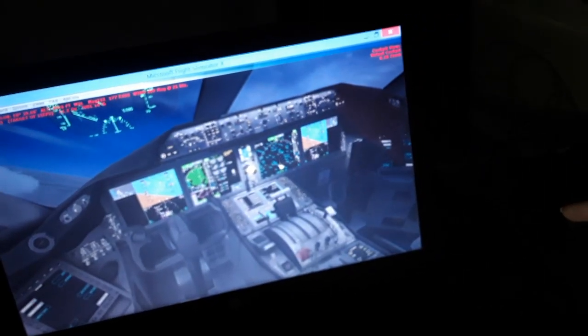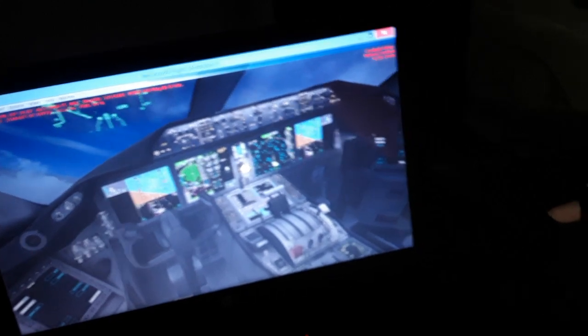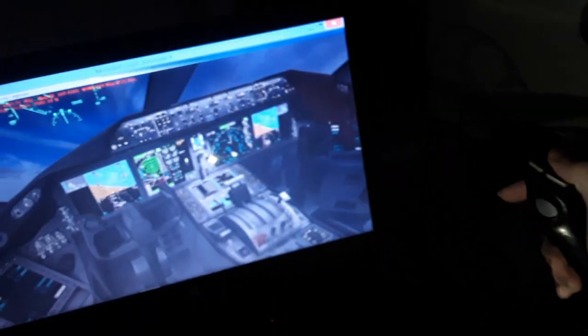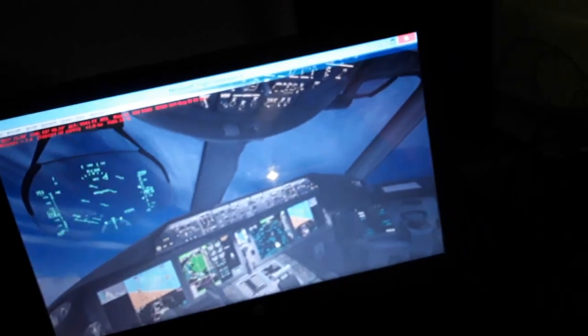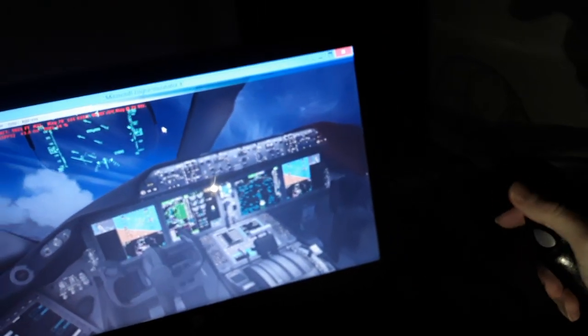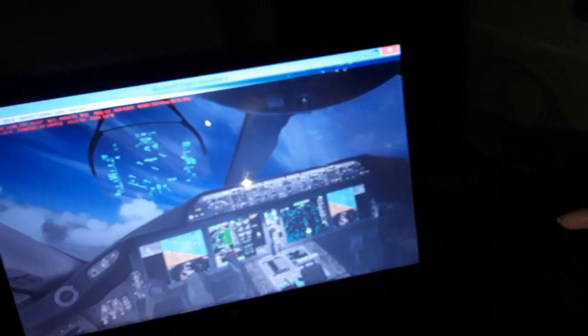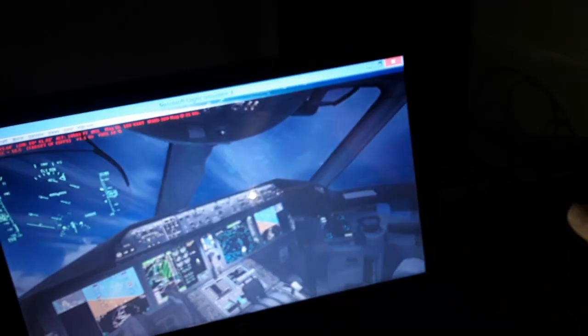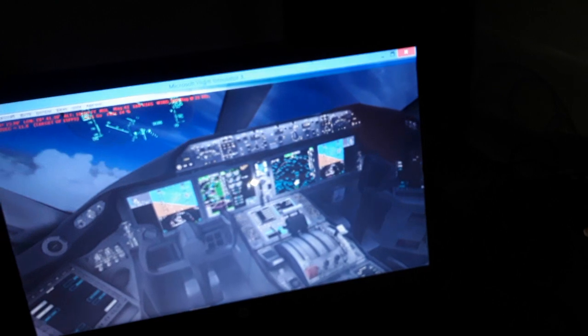Use a little bit left rudder pedal to make it a little bit faster if we need. So we align now with the rudder pedals also as we turn. So we can leave the hands off the flight controls, no problem.